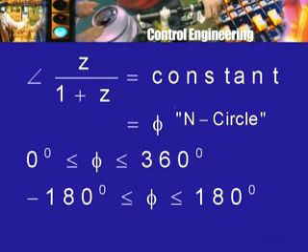There is a contour map for the gain, and there is a different contour map for the phase shift. And then in exactly the same way, as you trace the polar plot as a function of frequency, the intersection with the N circle at each point will give you the phase shift at that point. So, this is the set of M circles and N circles.